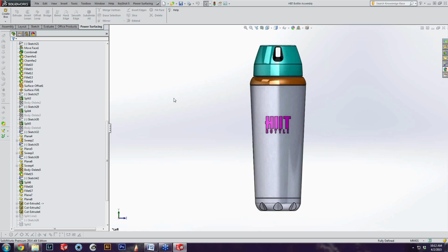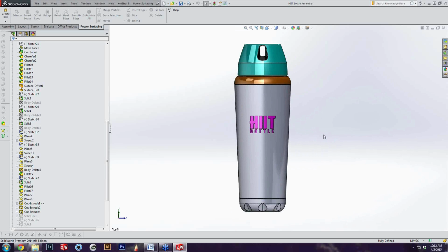Hey Vic. Yeah. I'm just going to jump in here and mention something real quick. Users of KeyShot 5 Pro have the benefit of using the NURBS option. So in their case, you don't really have to consider what that value is set to. You can keep that at a low value, so it's fast and speedy to transfer over. And then once you're inside of KeyShot, you can click that NURBS button on the ribbon to switch it to the NURBS mode for the perfectly smooth surfaces. Oh, that's awesome. But like you mentioned, for the HD users, this is a very important thing to consider. Mm-hmm. Cool. Thanks for jumping in on that.